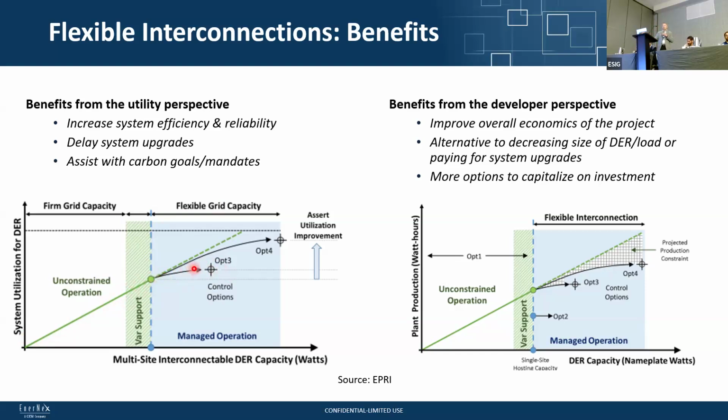So option 3 might be overly curtailed. This might be considered the static or time-varied, where you can't connect or you can't over-generate. It allows more operation in there, or more capacity, but it's still reduced. And then you may have what we're showing here, like option 4, where it's increased utilization, but again, it probably comes with more complexity, like we were talking about, some sort of advanced DERMS system or control system that allows for that.